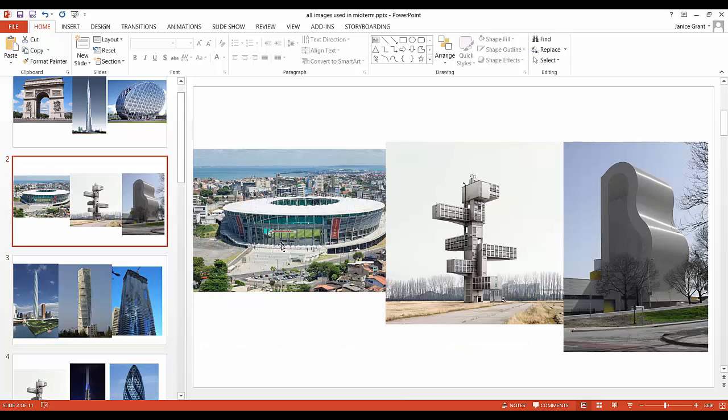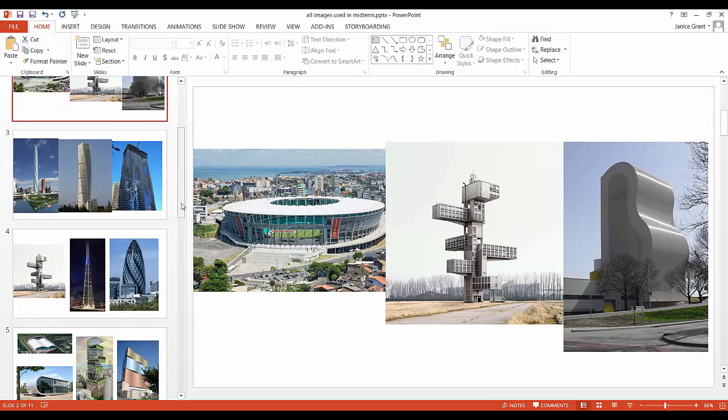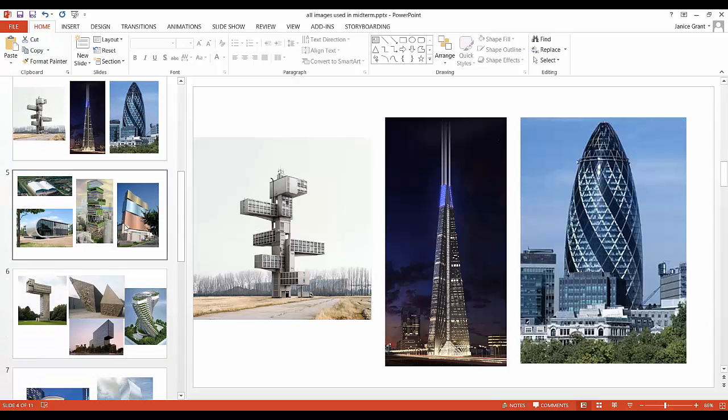Sometimes, like in this example, you may create a void. A void is right underneath create form, and it helps you to subtract the geometry. So this hole could be a void, or you could actually draw two pieces of geometry and use the cut tool, which is in the mass modeling, to cut one geometry out of the other. So very similar to AutoCAD and Rhino and other programs for creating unique forms.